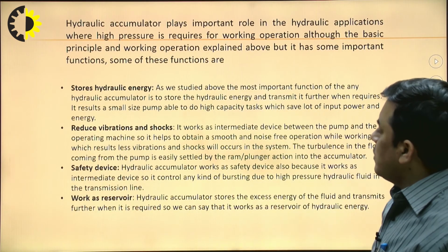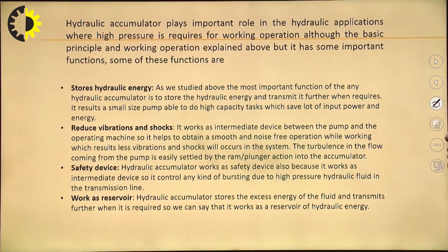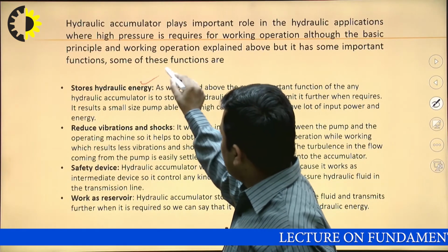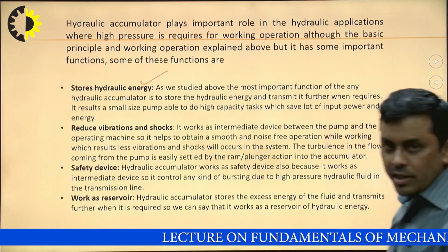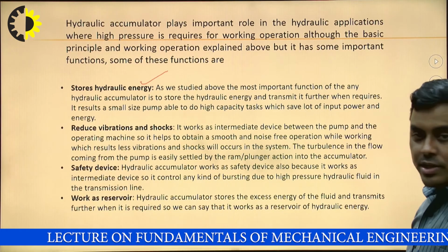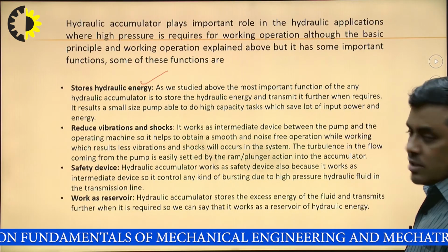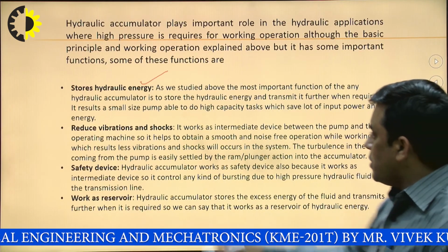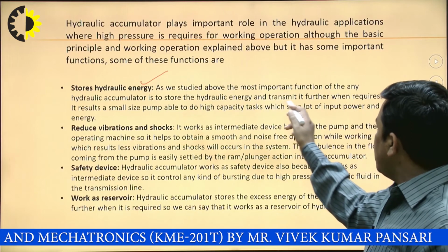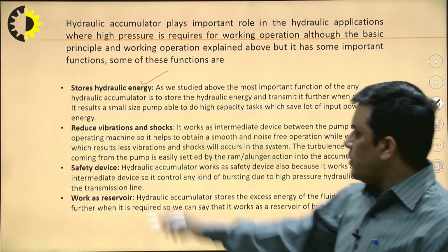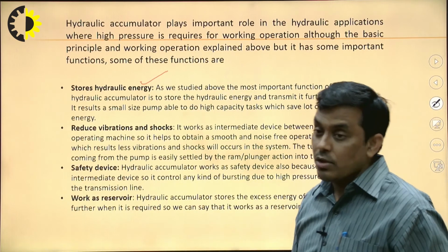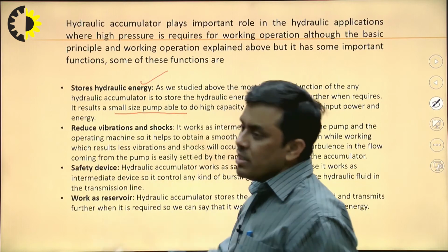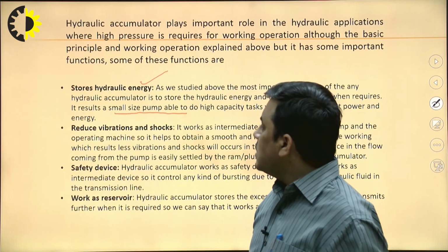Here the working is explained, and what are the different purposes of a hydraulic accumulator? The very first purpose, it stores hydraulic energy. How it stores the hydraulic energy has already been discussed. As we studied above, the most important function of any hydraulic accumulator is to store the hydraulic energy and transmit it further when required. So it results in a small size of pump.